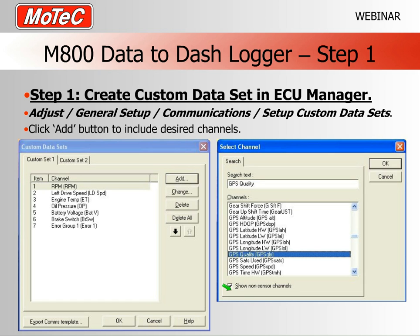For example, there are some channels that come into an M800, and here I've shown GPS as one of them. Now, this is not a sensor, for example, like an engine temperature sensor. This is another data stream that comes into the M800, and if you need to transmit your GPS data, you need to have this checkbox ticked, or else you won't be able to see these GPS parameters in your drop-down list.